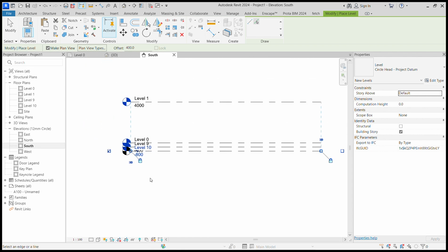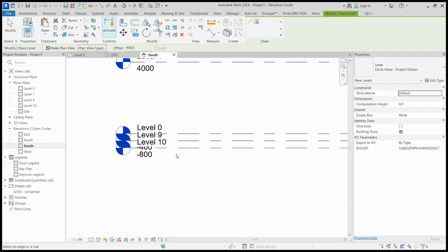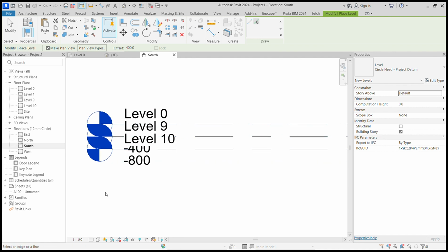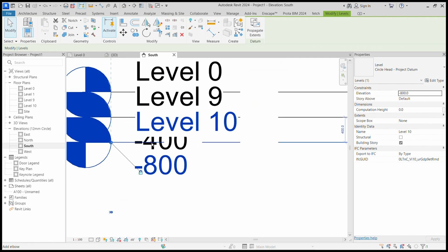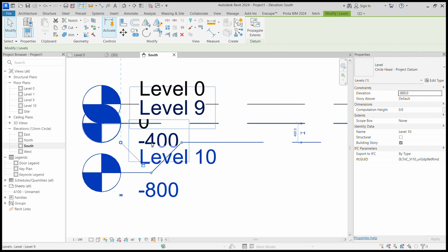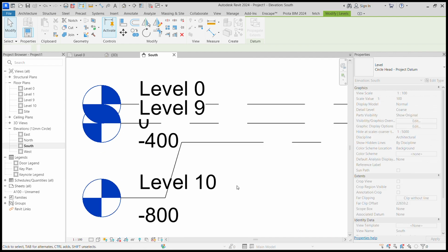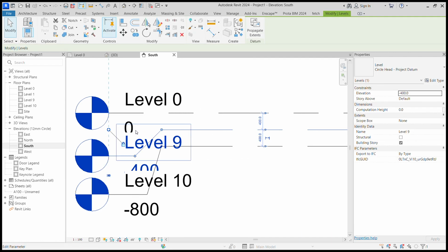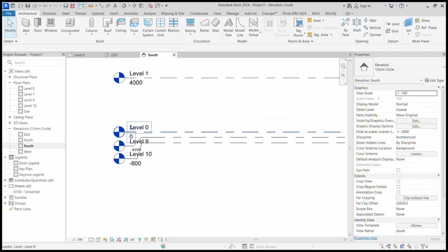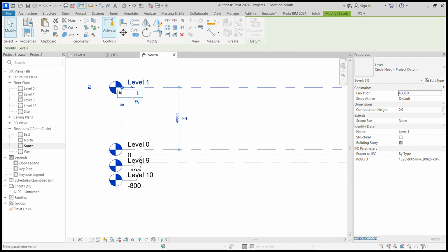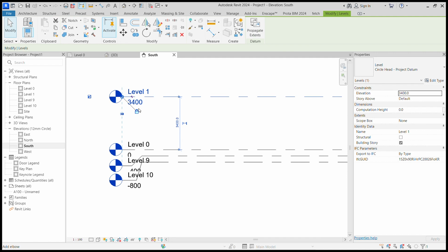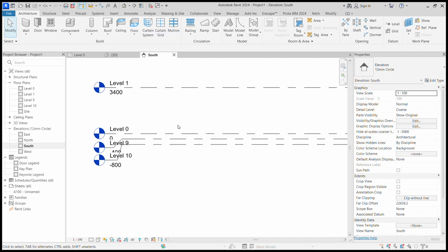So you can see you have all these ones here. You see it has been combined, but you can separate them. When you select, you see something here, it's like a brick. When you click it, you can drop it down nicely. Maybe you want your room from your ground floor to your roof to be, let's say, 3,400. These are in millimeters. So let's say you have these levels. So these are your levels.